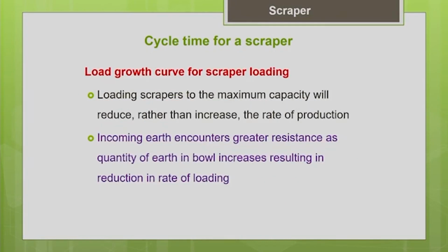Another important concept which we need to know is the load growth curve for scraper loading. We commonly believe that when we fill the bowl of the scraper to the maximum capacity, we are going to maximize the production. This is the common belief, this is the common assumption, but that is not true. People have done studies and they have proved that when you try to load the scraper to its fullest capacity, the production starts reducing beyond a particular time.